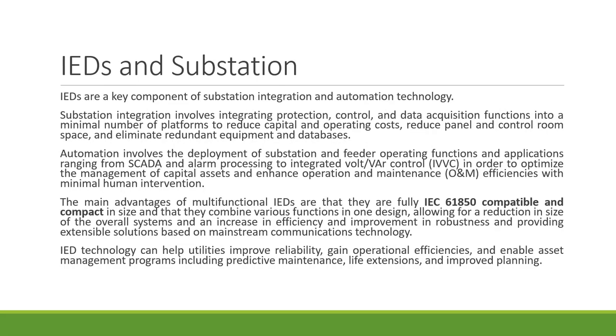Under that, you know that there is a need for replacement of an oil transformer or distribution transformer. If you have this IED technology, it will communicate to you that the level of oil is low, or it has become too thick or too dark, so just replace it because it cannot perform its function. So proactive maintenance can be done. The engineer, or whoever is concerned, will go and replace it. And so it is going to increase reliability of supply, because there will be no outage.